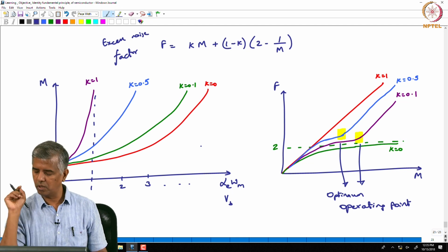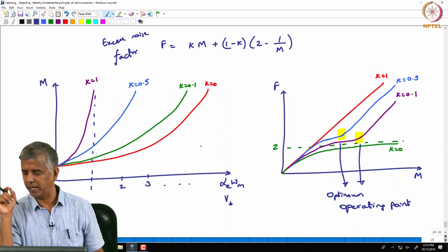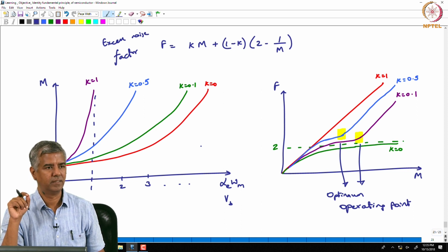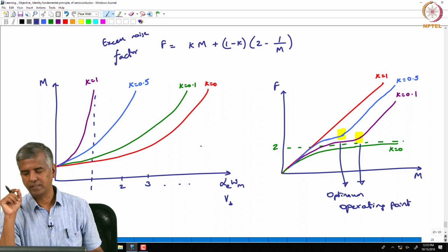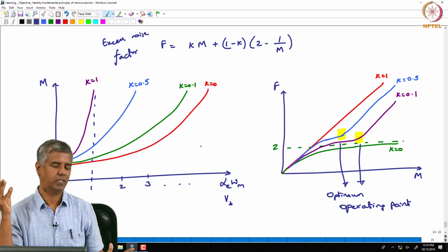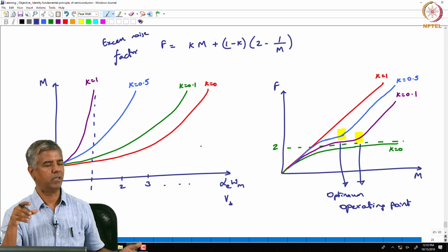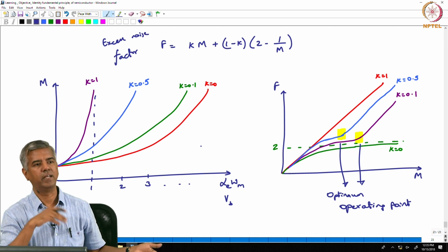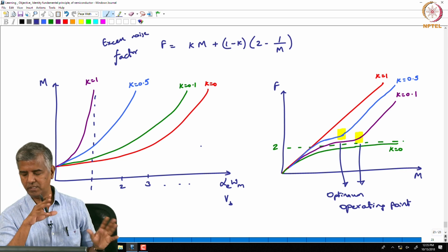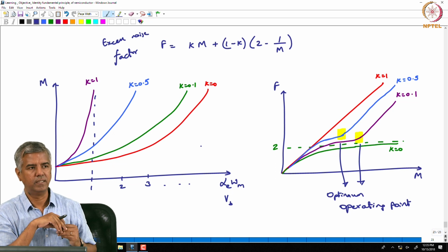It also tells you that the optimum gain you can extract from indium gallium arsenide is going to be lower than what you extract from silicon, just because indium gallium arsenide has a larger k value, closer to 1, than silicon. So that is just a material property by itself. Do you understand that?